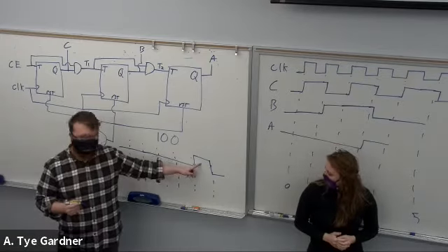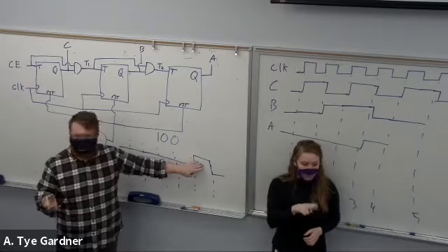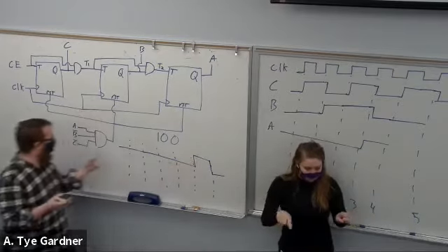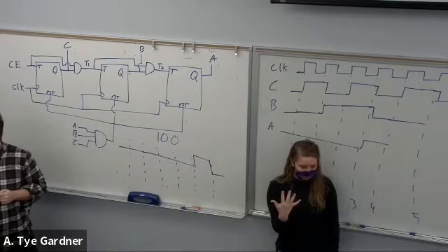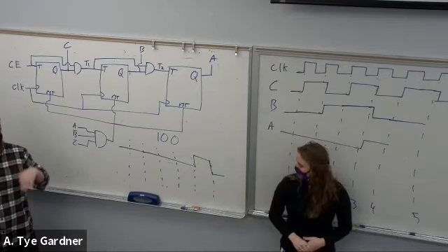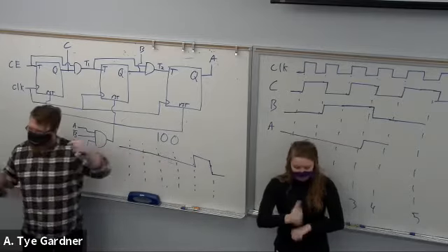So this, then I can use as a pulse indicator to say this is 1 clock, 1 rising edge for every 5 counts. Count to 5, reset, count to 5, reset. So this is how I could build a clock divider of 5.